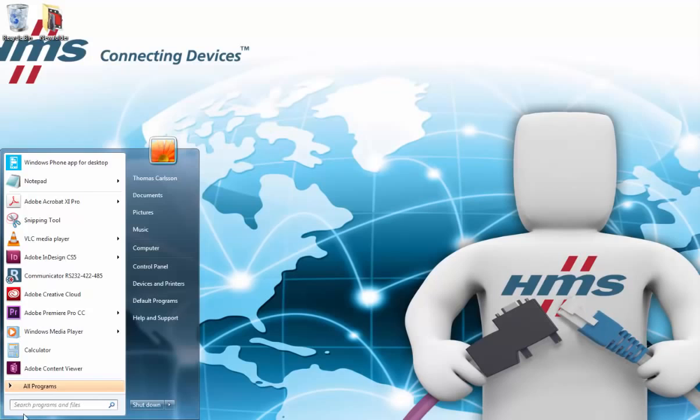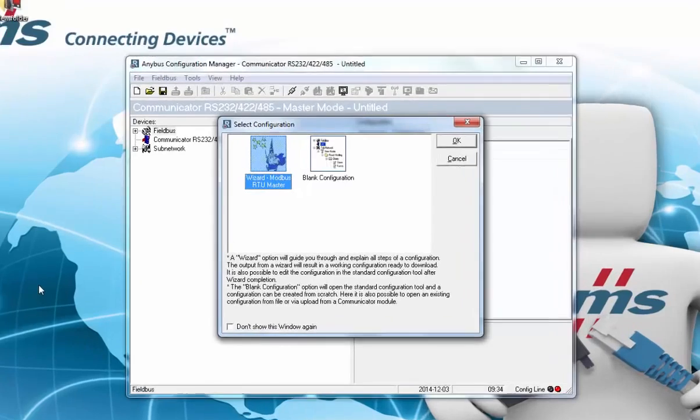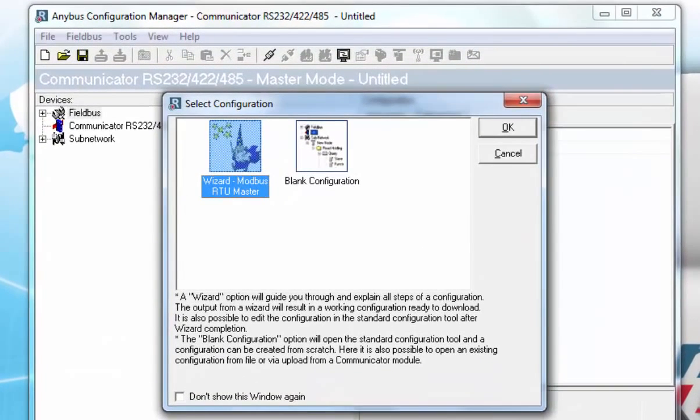I start the Anybus Configuration Manager, which is included in the product package from HMS and is also downloadable from anybus.com. Before I start, I can choose if I want to use the wizard mode, which includes a lot of default values and is a bit quicker, or start a blank configuration from scratch. I choose the wizard mode, which is best for a Modbus RTU device.